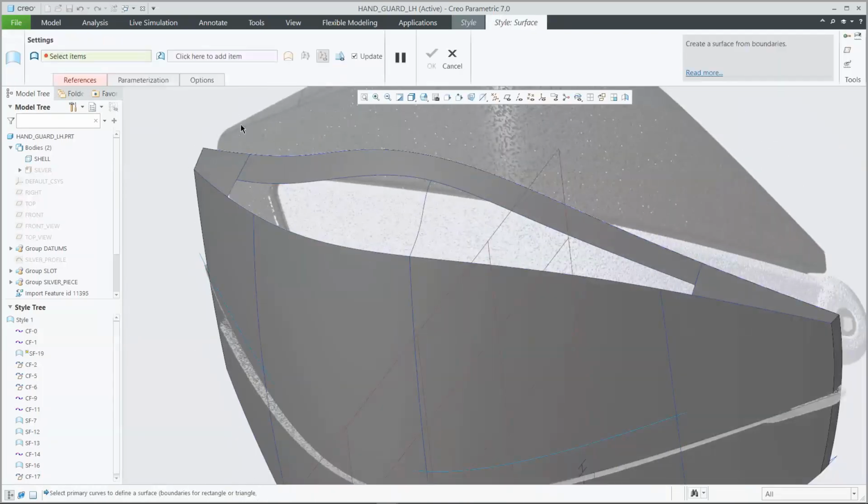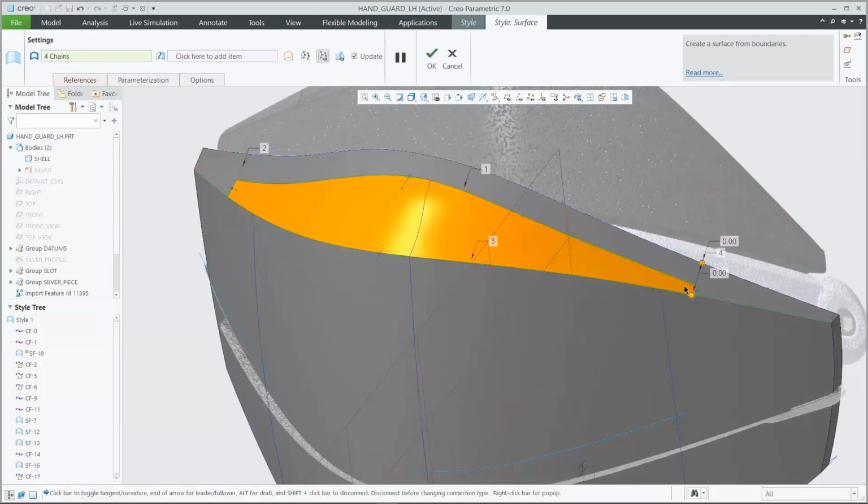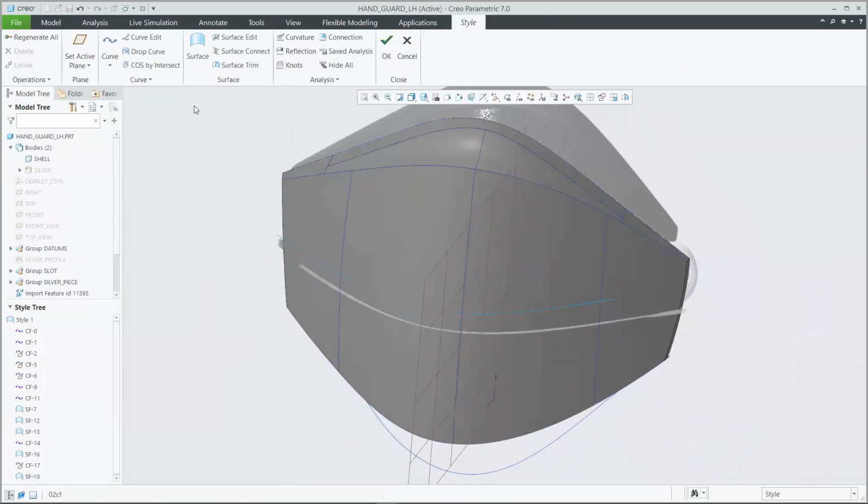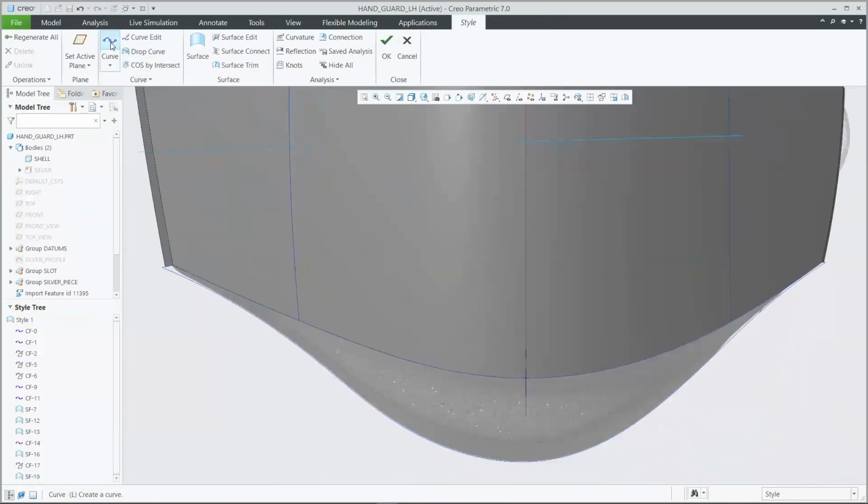And with that, we're good to go ahead and create a last surface up at the top here. And while you're defining that, you can define the transition into the surfaces at any point as well. Just add in that controlling curve that we have in the middle. And we're all good to go up at the top. And pull in that controlling curve. There we go.